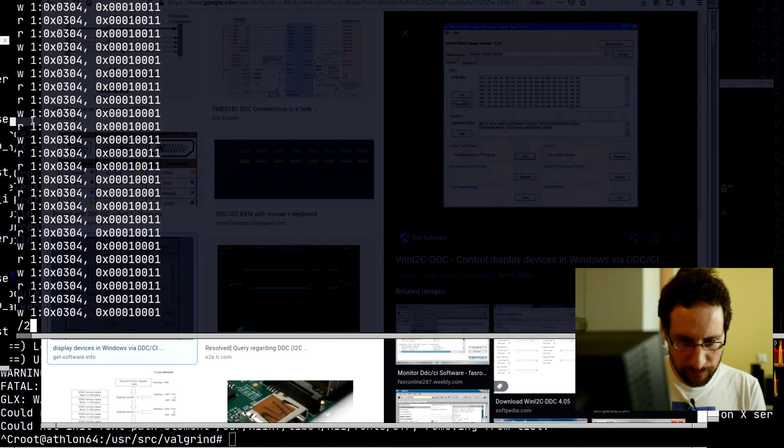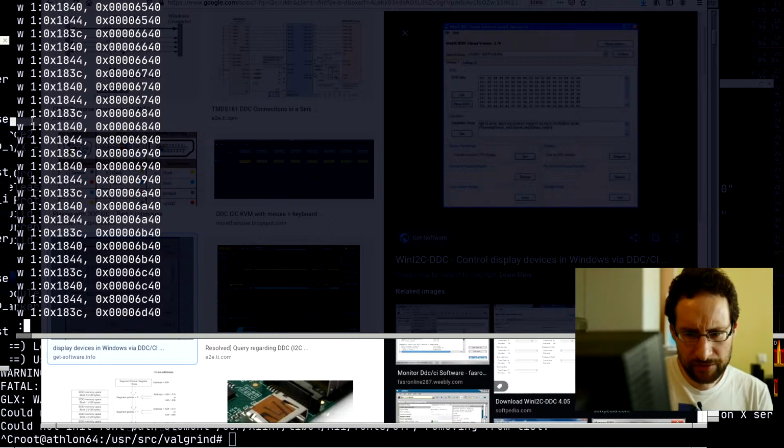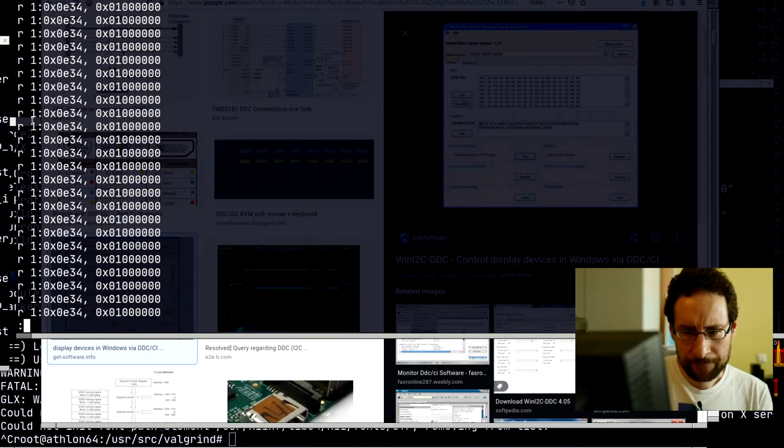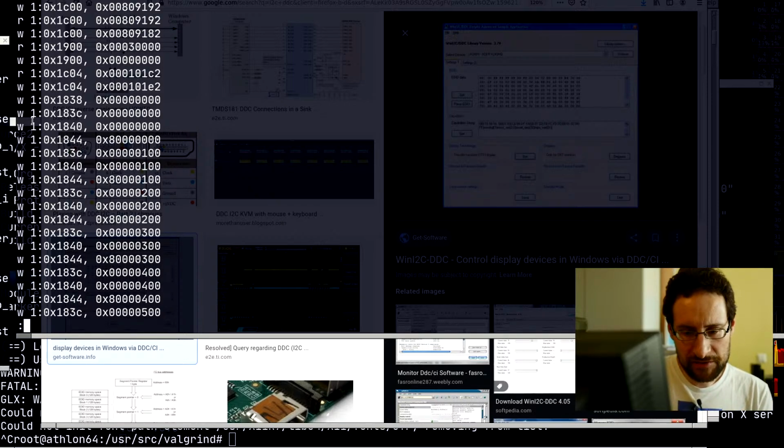Let's maybe fast forward to some frame buffer write, which is this, and let's scroll back a little bit. What was before 1C4? What is this doing here? Yeah, some of this stuff should be mode settings. So somewhere after DDC probing, reading over an I2C bus display data channel, and your display's EEPROM or flash, whatever ROM stuff, serial flash, eventually mode settings.